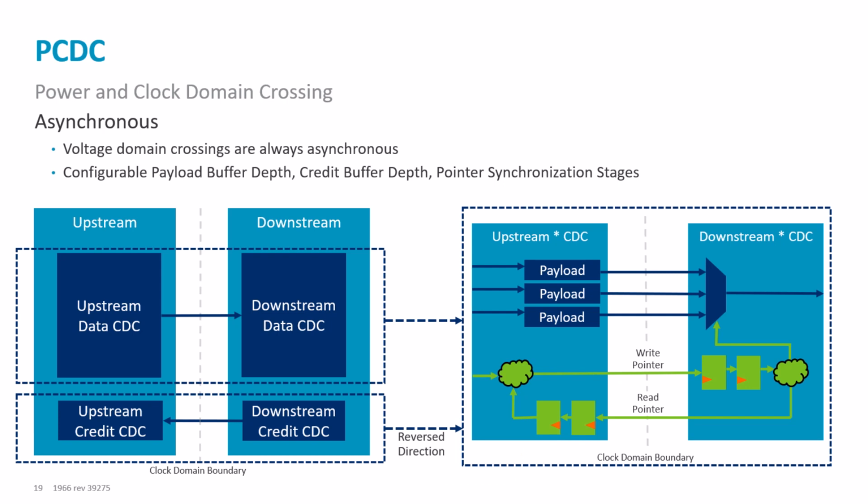However, if full throughput is not required on a specific path, the depth of the buffer can be reduced to meet the bandwidth requirement. This reduction provides corresponding benefits in area and the number of wires that are required. To configure the buffer depth, set both the async data buffer depth and async credit buffer depth configuration options accordingly.